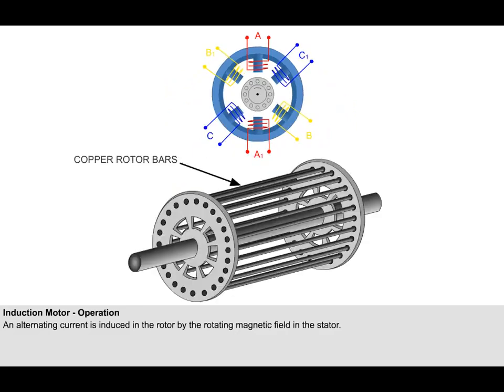The rotor usually consists of a cylindrical laminated iron core which has a number of longitudinal bars of copper evenly spaced around the circumference. These bars are joined at either end by rings of the same material to form a composite structure called, because of its shape, a squirrel cage. The rotor bars are made of very low resistance material so that a large current can flow through them.